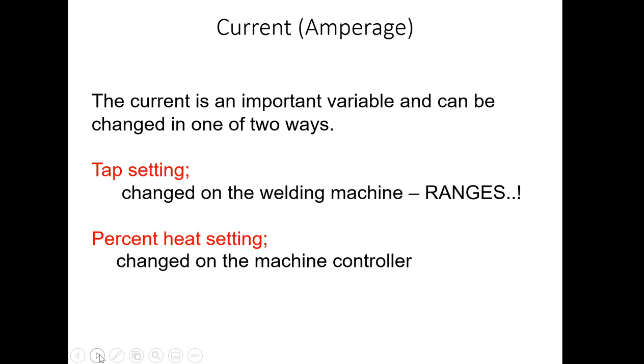Now, there are some complications when you're setting up a machine for the very first time, complications in setting up these tap settings. You need to know what range, and it has to do with your duty cycle as well. There's more to setting up your tap settings than just finding a position that works.